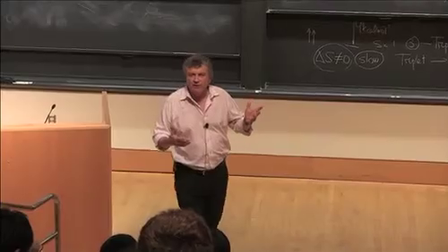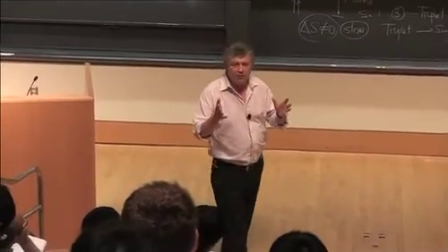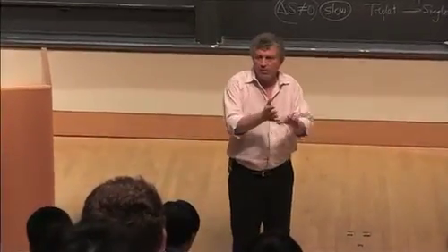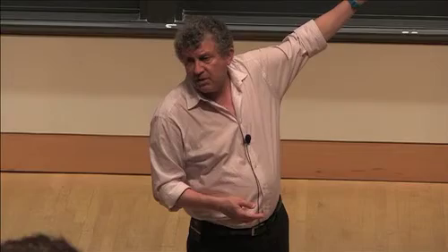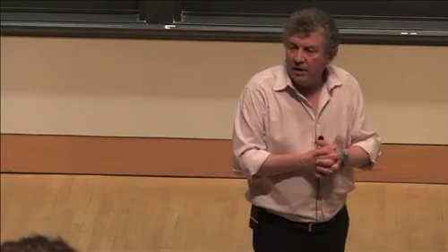Essentially, what we have seen is that when you decrease the Damköhler number below some critical value, extinction would happen. And so you can relate the extinction value to this scalar dissipation rate, chi. And so that will be essentially the use of this mixture fraction variable. In other words, what you do is change your normal coordinate to this mixture variable coordinate.